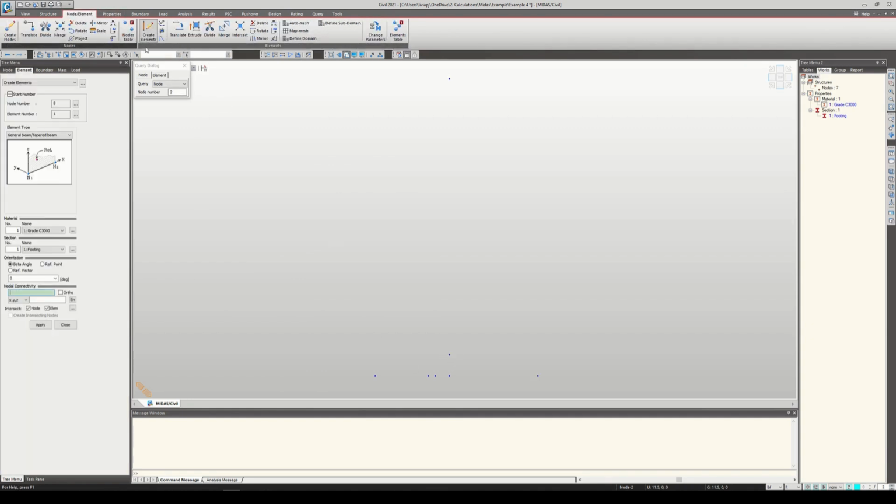So now that we have the footing, let's draw our footing. We'll go to create elements. You'll see here that the material name and the section name will pop up here. So once we do the wall, we will need to change it to the wall. So first let's draw the footing. From here to here, there's our footing. And if you don't have the 3D mesh on, you can just click here, Control H. It will hide it and unhide it. I like to have it on.